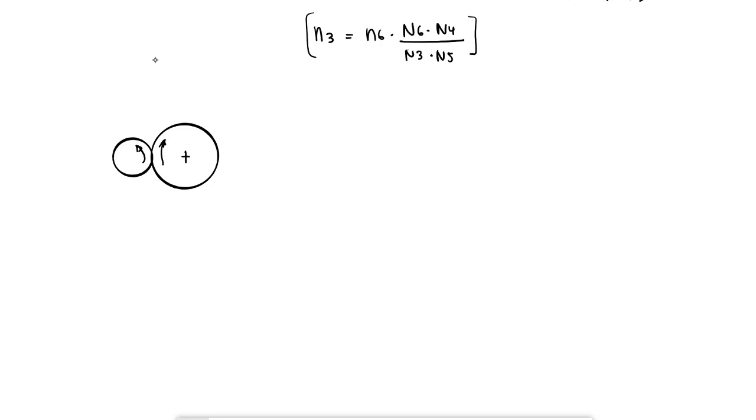If I isolate gear 3, the fact that it is rotating clockwise is because there's a force pushing it up. It's creating a torque that is causing that rotation, and we call that the tangential force, W with a superscript T.